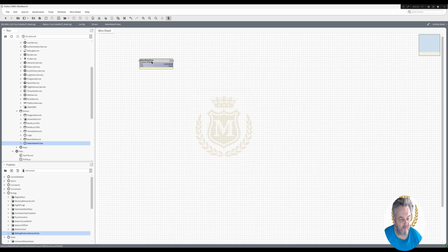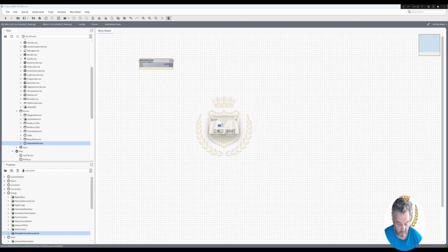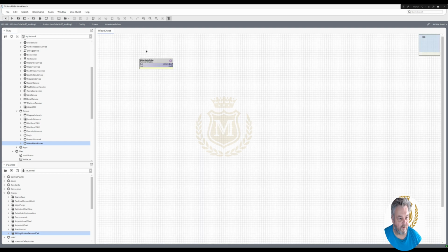And that's going to be 10 pulses is equal. So let's just set that to 10 at the moment. We don't need the 0.0 because it's not decimal, so let's just take that out. And that's just a pulse. So we've got water meter pulse there. So that's 10 pulses, and we need to transform that into meters cubed first.